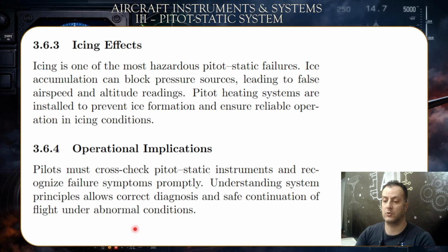Let's say one of the pitot tubes, to the left or to the right, has been blocked. You should isolate the problem, and by the way, you should also deactivate the autopilot, especially if it's getting its reading from the faulty pitot tube. Otherwise, it can bring down the airplane. So you would need to rely on the other instrument, and preferably go back to the runway, to the airport, in order to fix the problem.